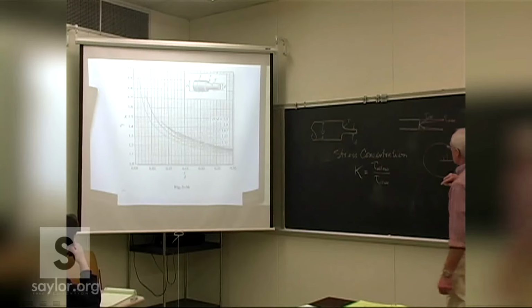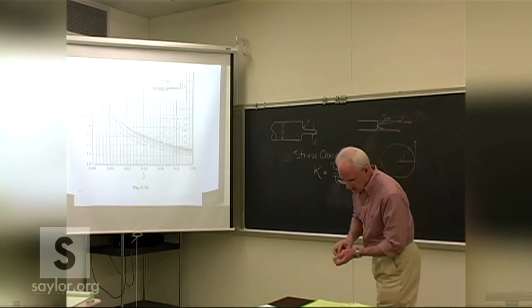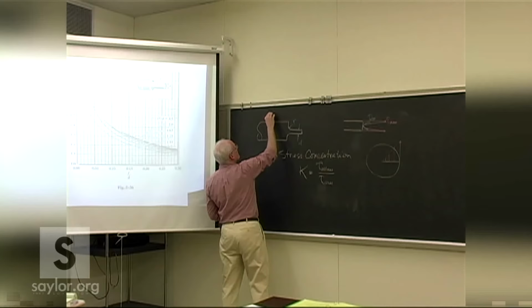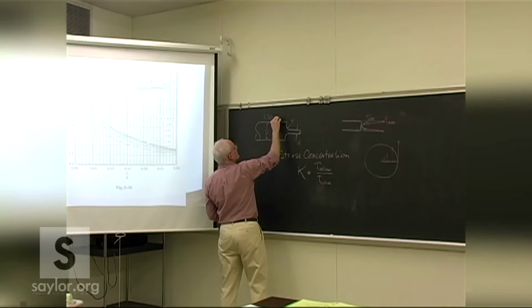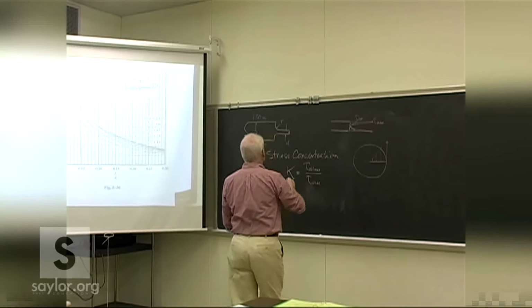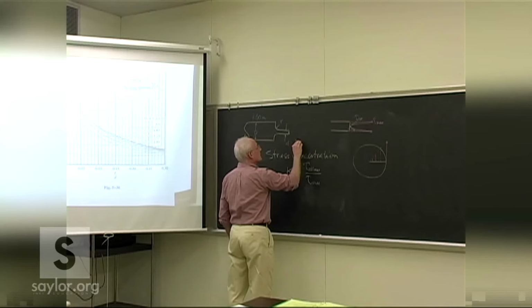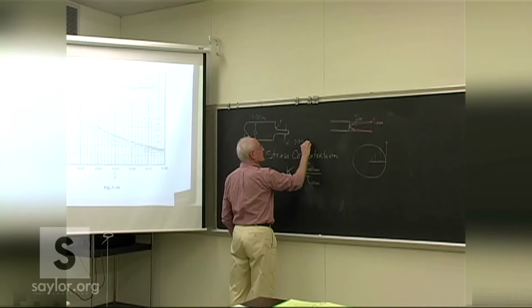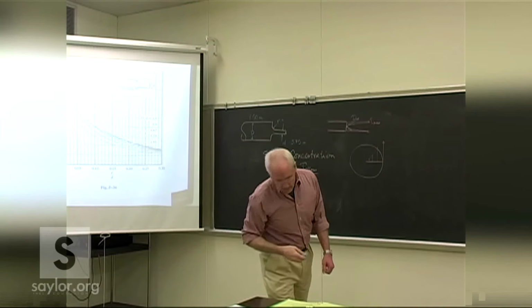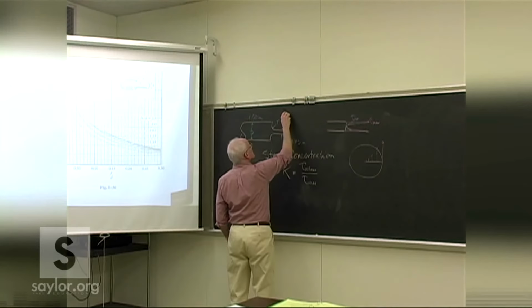Imagine we have a step shaft like that with a major diameter of 7.5 inches, minor of 3.75 inches, and a fillet radius of 9/16. Good old American values.